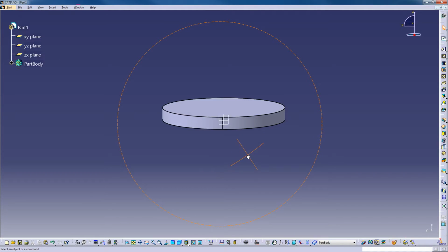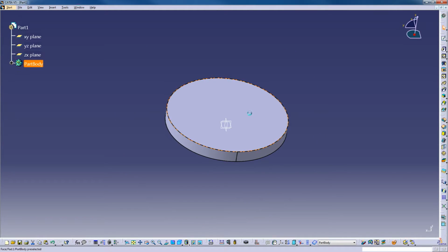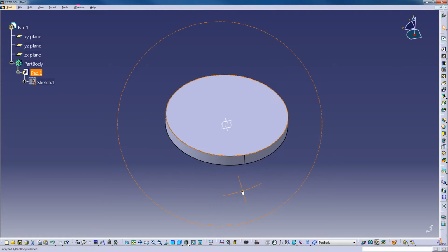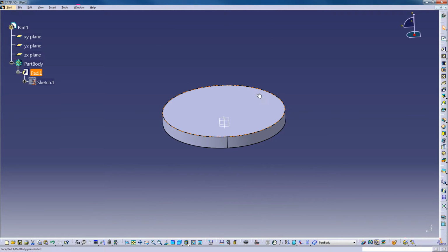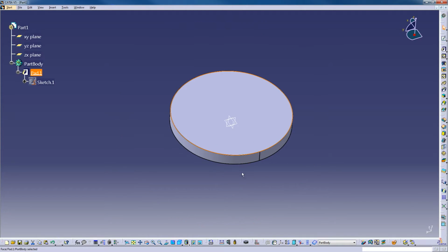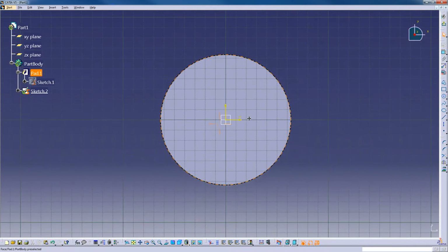So what I'm going to do is just show you. I'm just going to pick the top of this, right? Later, when we get further down the road, there are a lot of decisions on which surface, which plane should I pick, so that I make the part in a proper way that myself or someone else in the future can edit well, right? That becomes a pretty big topic. So I'll pick the face, I'll pick Sketcher, and we go into the environment.